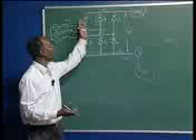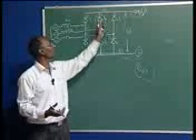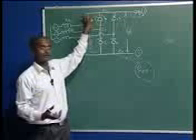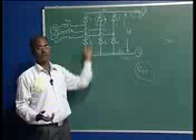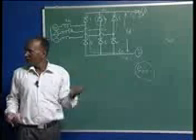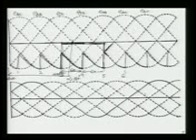Here the change of the valve voltage will only occur if there is any conduction in the upper limb. If this is conducting or this is conducting, then it is going to change. A change here will not change here, because at that time the same valve was conducting. So it will follow, even though the 6th valve is fired, up to here, and here 1 is going to be fired. So it will go up to this portion. This is the valve voltage I am drawing, the thicker line.